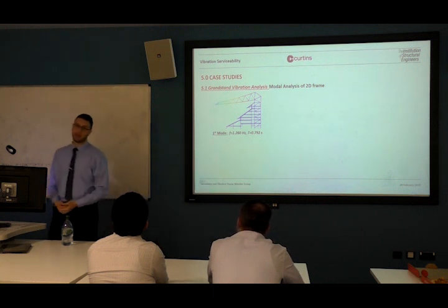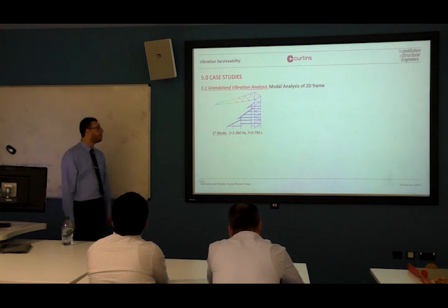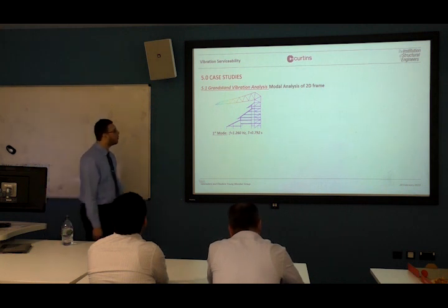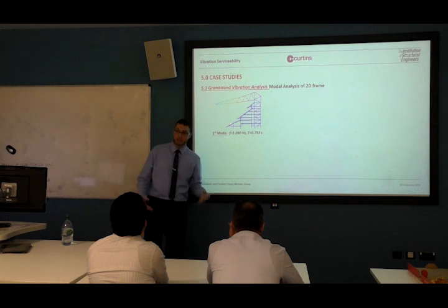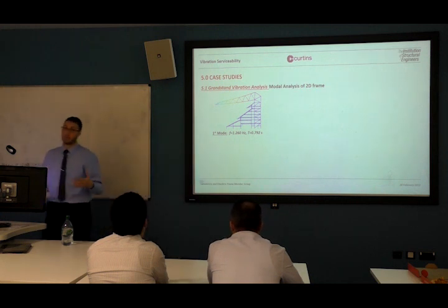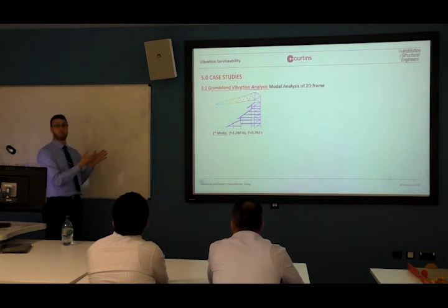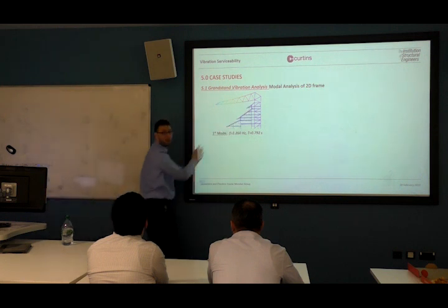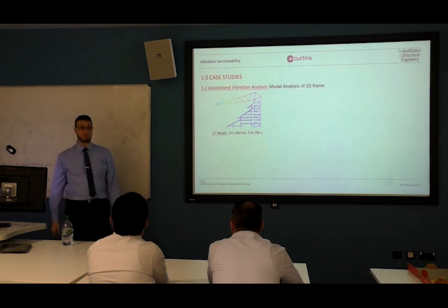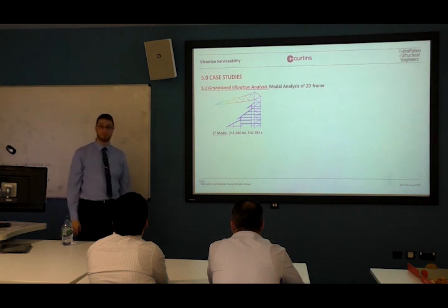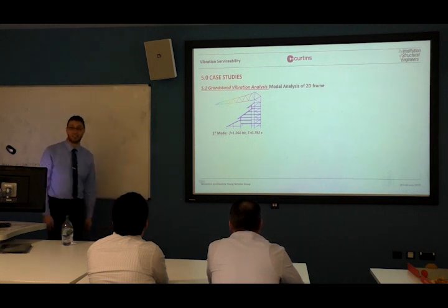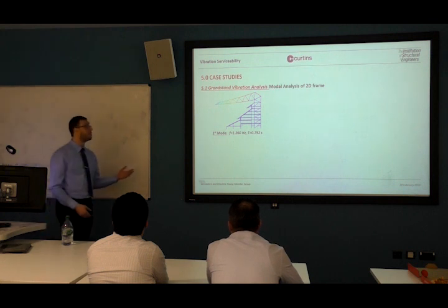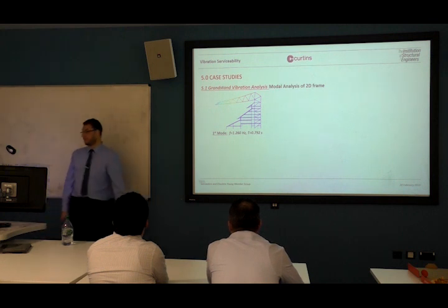It's much less than 6 Hz. But are we really concerned about the roof moving? Can we, as a crowd, actually excite this mode? If we are sitting here, do you think we can? No, we can't. So the first mode is something that we're not interested in.